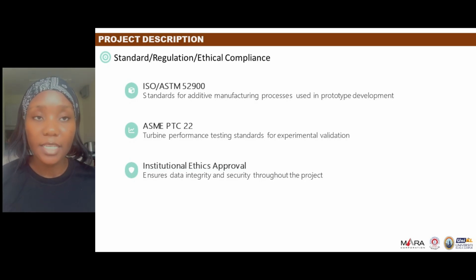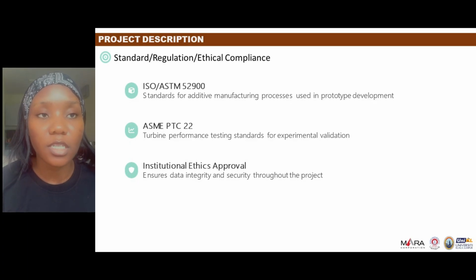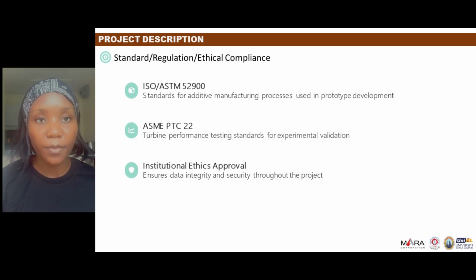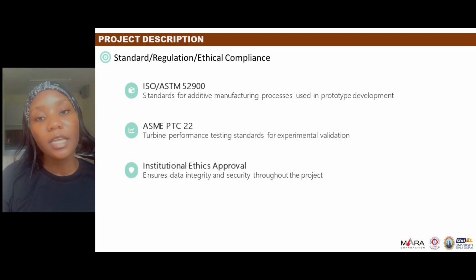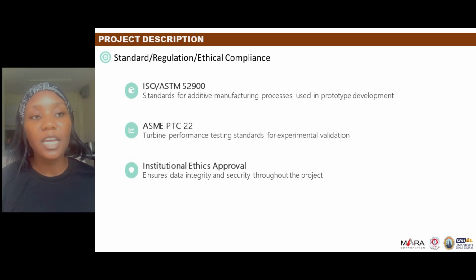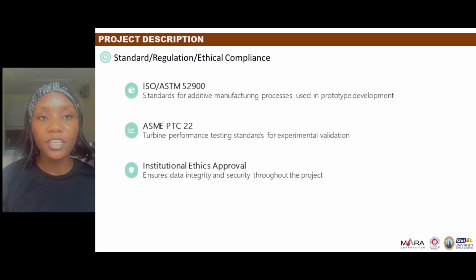So to validate the optimized turbine blade tip cavity designs, experimental testing is essential to ensure that simulation predictions translate to real-world performance. The fabricated prototypes will be installed in a specialized test rig which is designed to replicate key operating conditions of a gas turbine, including realistic temperature gradients and pressure differences across the blade tip region. Thermal imaging cameras will be used to capture detailed high-resolution surface temperature maps of the blade tip. This infrared thermography provides spatially resolved data showing how effectively each cavity design cools the blade, pinpointing any